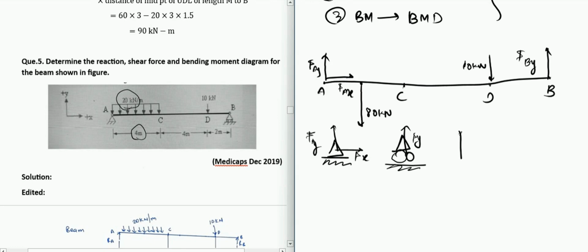And if there is a fixed cantilever beam, then we have to give forces in x and y and also a moment, so there will be three unknown forces. Here there is one unknown force, and here there are two unknown forces. Those are the reaction forces you need to give according to different types of supports.